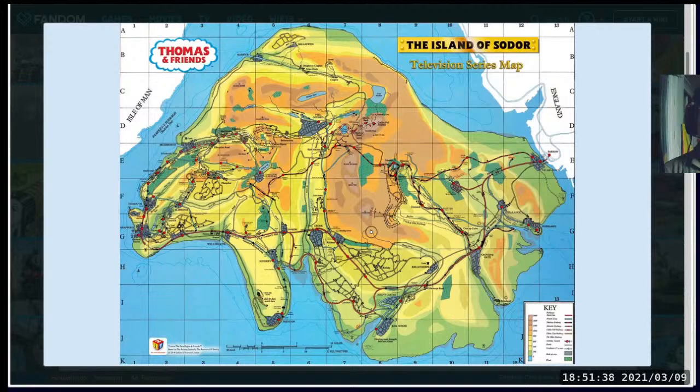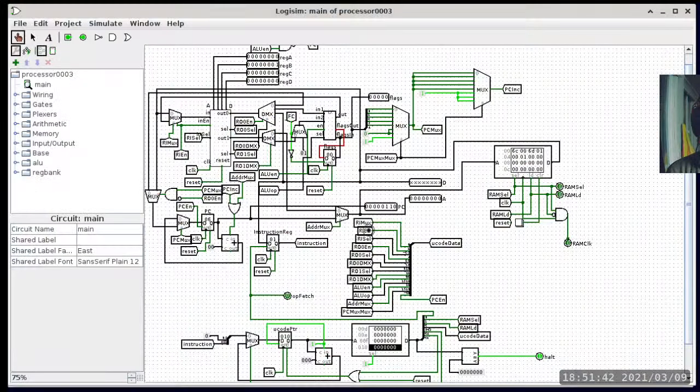So just imagine you have a whole bunch of little trains, and they go from one thing to another thing. These are the railroad switches. The multiplexers and the demultiplexers are railroad switching devices. All they do is say, okay, the input track is going to connect to this output track, or one of these input tracks is going to be connected to the output track. The rest halt. You cannot get through. So that's kind of what it is.